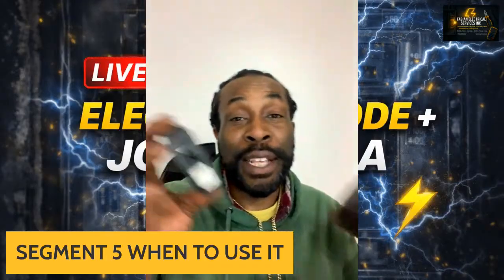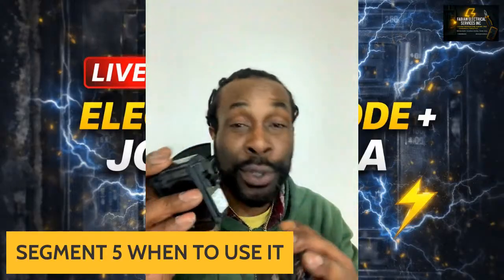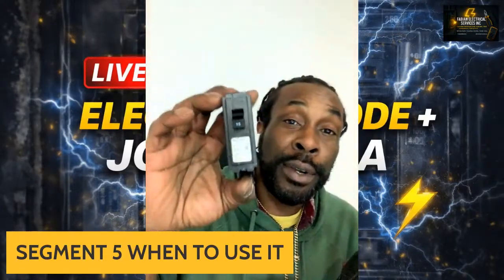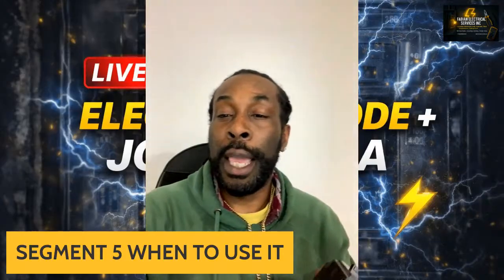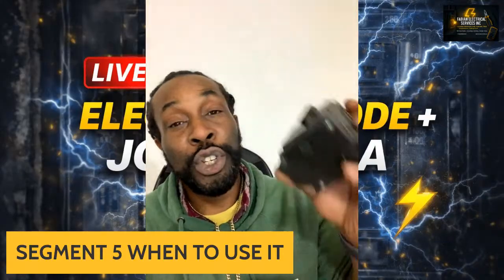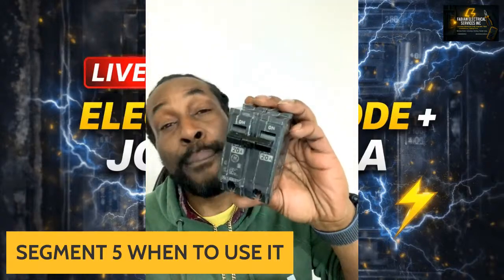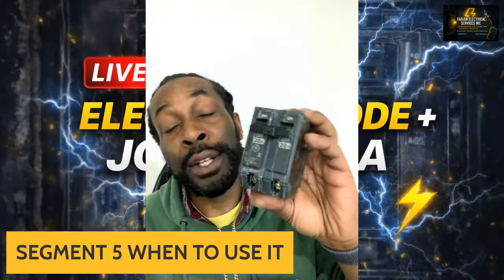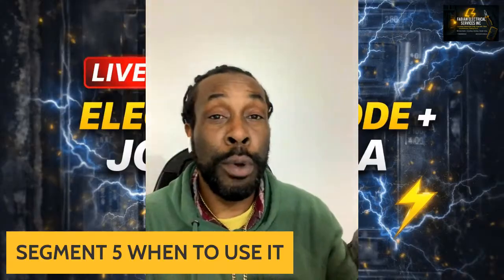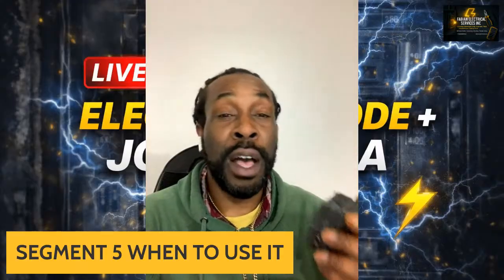You cannot mix and match inside of one of the other panels. This is a Schneider; it goes into a Schneider panel. Again, this is a GE type breaker, 20 amp two pole. This goes into the GE panel. Again, you don't mix breakers inside of other panels.